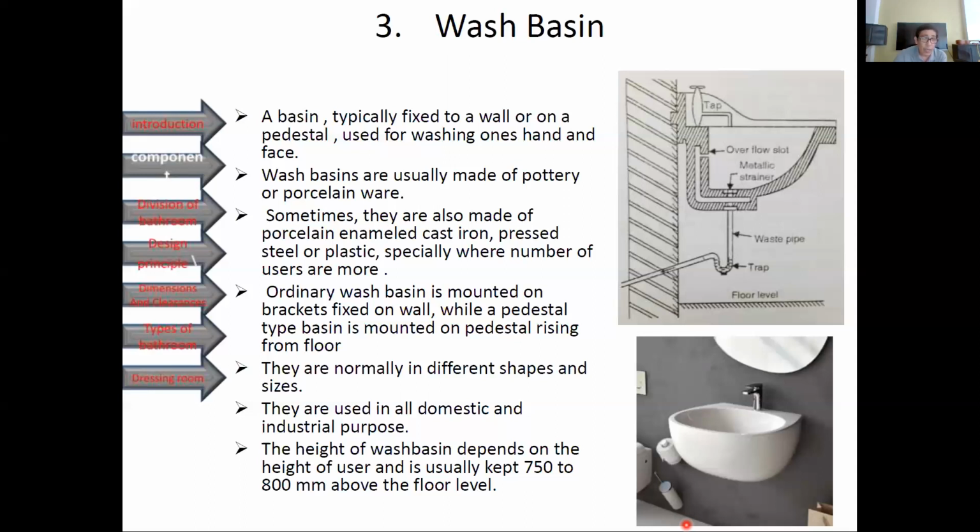The pedestal accessory is sometimes detached from the lavatory. So you need to make sure that if the pedestal is attached to the lavatory, it will be mounted on the floor. But if it's two components, where the pedestal is an accessory of the lavatory, you need to attach the lavatory to the wall by a bracket.